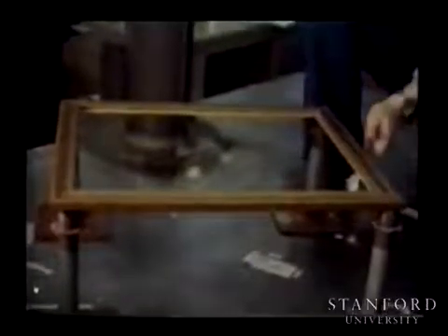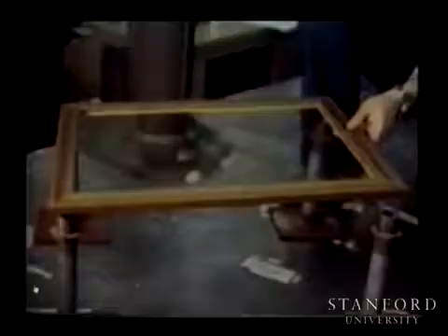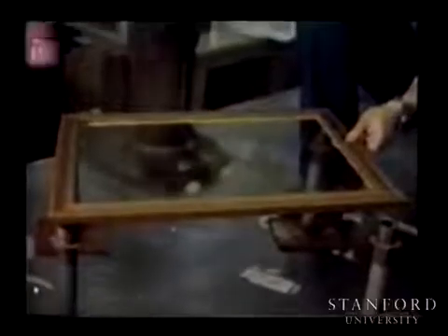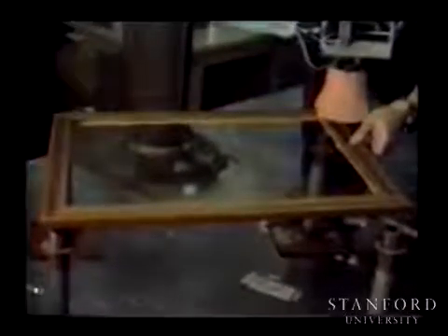All of this cannot be done without force control and compliant motion control. So you put an error and still you are doing the same task. Dealing with uncertainties requires you to be able to control the compliance. This is linear compliance, but we can also do rotational compliance. So zero moment. When you push to the left or to the right, you will have a zero moment. So if we could see the video back.